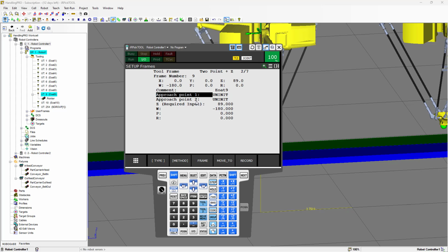You're going to select the approach point 2. In this case, the only thing that you can do is just rotate 90 degrees the axis forward of the robot. And again, you're going to align the environment tooling with the pointer that is in a fixed position. And you're going to repeat the same method. You're going to press shift and record. This is going to be recorded. And then manually you're going to change the Z height. And you can also change the WPR.